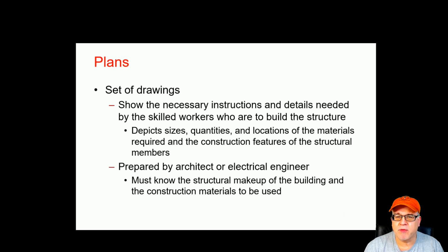But again, I've been involved with some contractors who do a lot of homes in a big subdivision, and they have specific floor plans. Those floor plans are laid out a specific way that shows where they want every receptacle installed so that they're more or less cookie cutter. And if you're the electrician working for that company, you need to understand what these symbols mean. Now, this is also a really good transition. As you learn all of the residential symbols, a lot of those will carry over into the commercial world as well, okay? So again, it's a good lesson to be learned here in this unit.